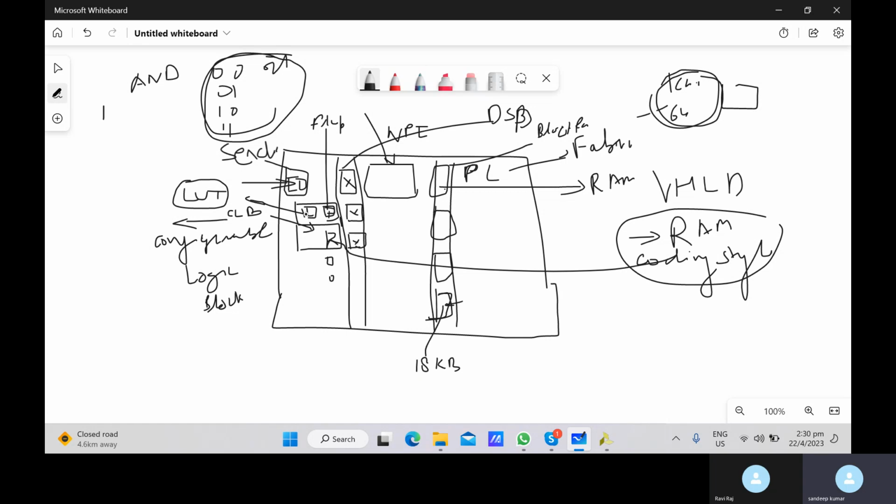So why not use an AND gate directly? This way it's very flexible to program. If there is any logic, like adder logic, how can it implement it in the LUTs? It can program the LUTs such that they behave like an adder. These LUTs are also interconnected with each other, so this LUT will talk to this LUT and this LUT will talk to this. It's highly sophisticated hardware which will be programmed based on your logic.